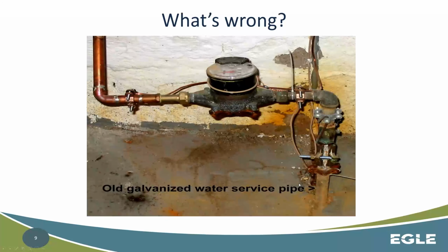The other thing that I see that's a problem here is talk about having dissimilar metals connected, right? You've got galvanized, you've got brass, you've got copper, you've got all kinds of things associated here, not to mention a whole bunch of electrical grounding, it looks like, which can also be an issue. Even though it's code a lot of times to ground to the water lines, it doesn't always do the best things for our water lines. And Matt will talk about that later today when he starts talking about corrosion control and corrosion in general.